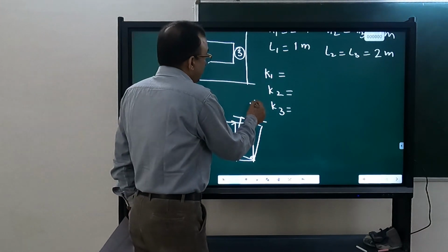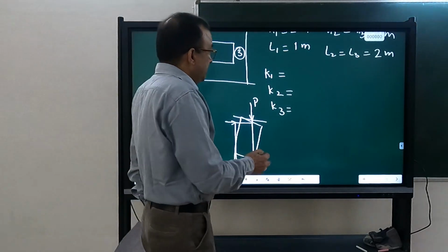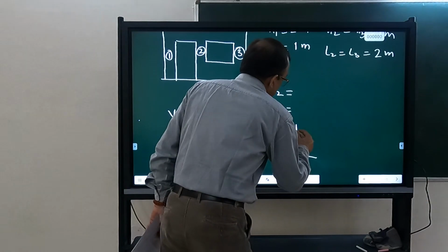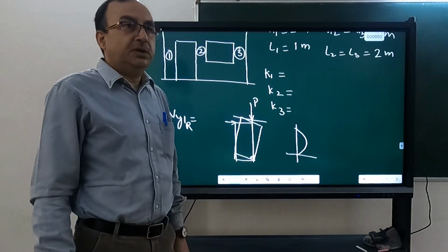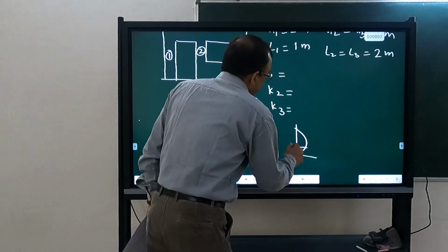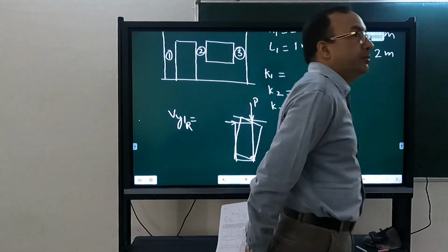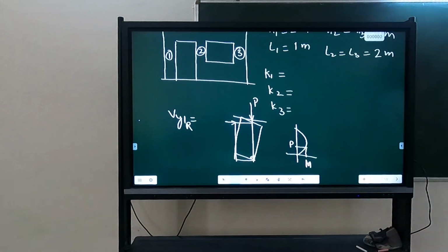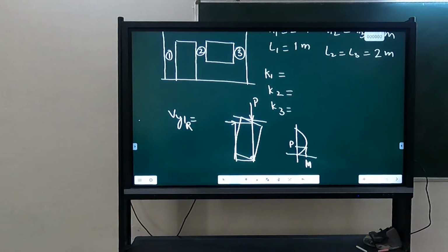So for this you need to calculate this vertical load P. Okay, and you have already done PM interaction for a masonry, not like this, but like this if you are ignoring it. Okay, so you can calculate for a given P what is the value of M. Can you do that? In the first tutorial we have plotted PM interaction curve for masonry. At any given force P, we can calculate the yield strength. How?